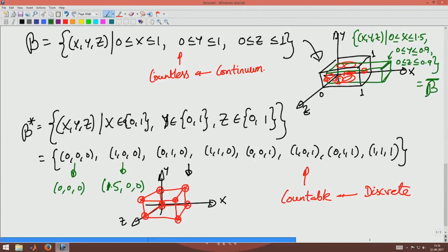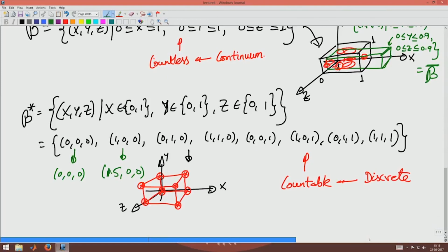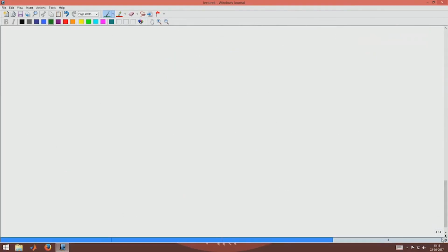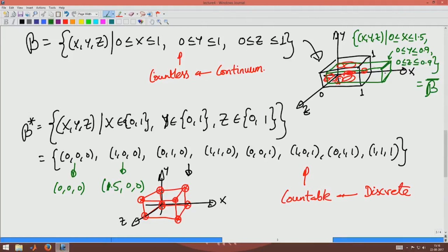Okay. So, now we understood what a body is. Now, let us understand two configurations of a body, that is, at a particular time I find what is the length of the body, what is its cross sectional area, where are its particles and so on, and then I apply a load, the body deforms and then it goes to some other configuration. Okay. For example, the green body that I showed in this example, after application of a force, is one configuration, and the black body beta is another configuration. Okay. So, we will assign names for these configurations.